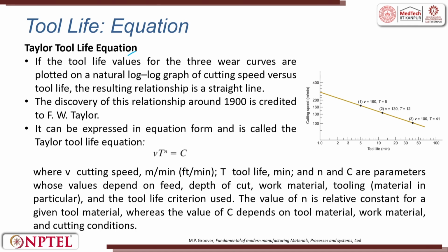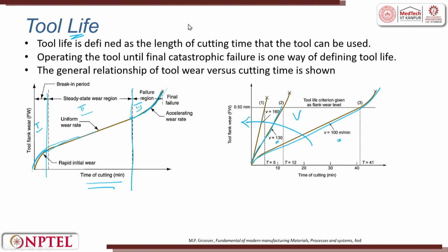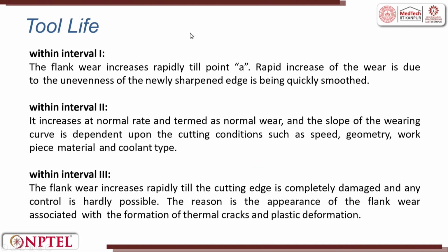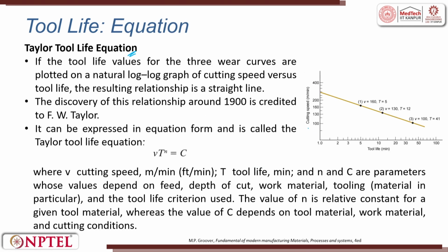So, the tool life equation: when I take the same plot and do a logarithmic plot, cutting speed versus tool life, I take the log value and then plot. It comes as a straight line, and the moment it comes as a straight line, I can express an equation.